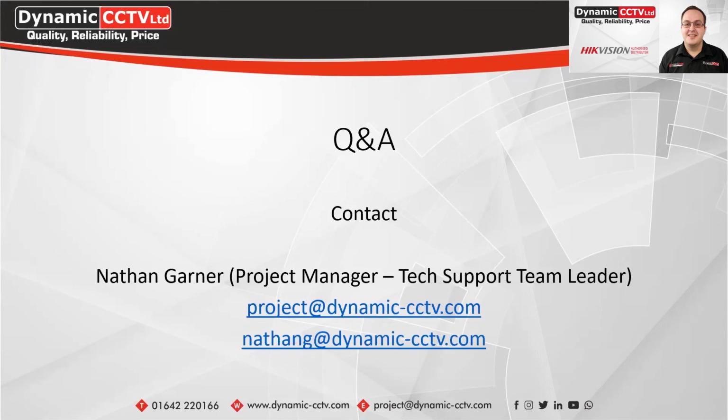Nigel's just put another Q&A in. If I use 2 megapixel cameras on facial recognition, can I get 16 channel analysis? So with the X model NVR, it's a maximum of 8 channels of facial recognition when the actual NVR is doing the face capture. If you use cameras with face capture, you can upload more libraries, but if the NVR is doing the brunt of the work, it is a maximum of 8 channels unless you use the higher end super NVRs for the facial recognition.